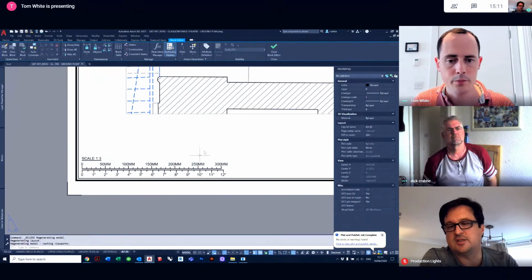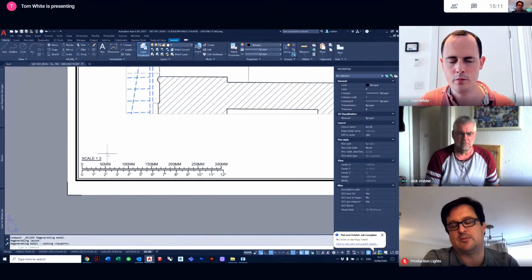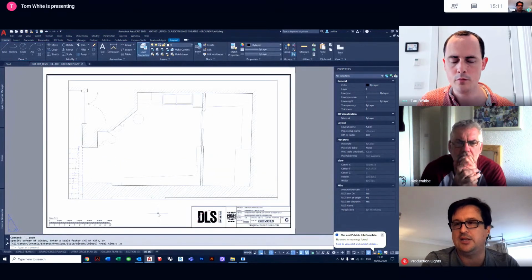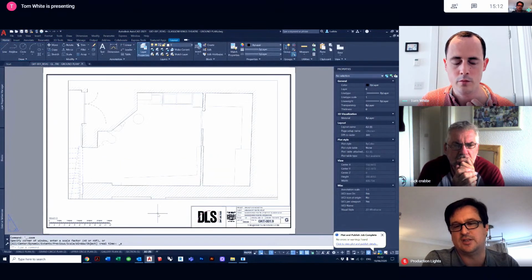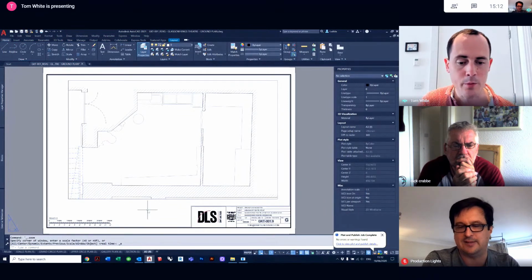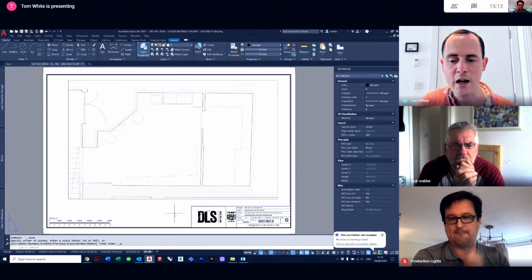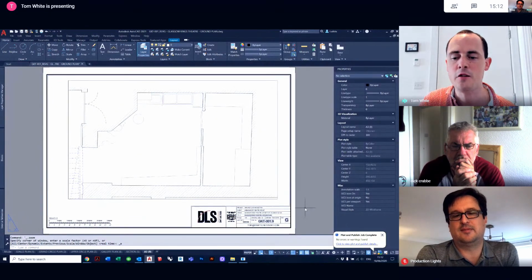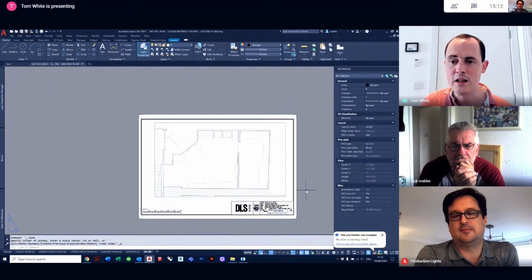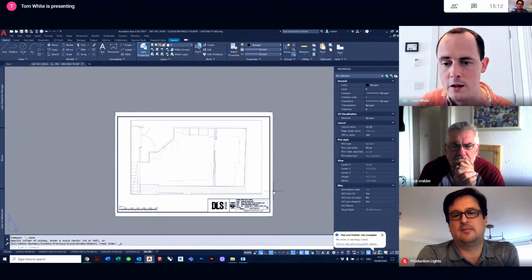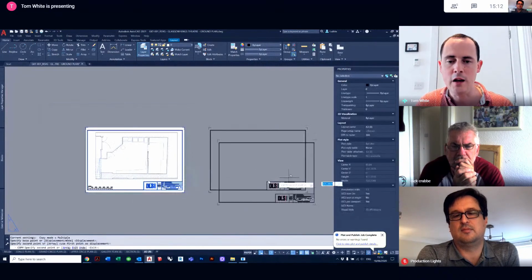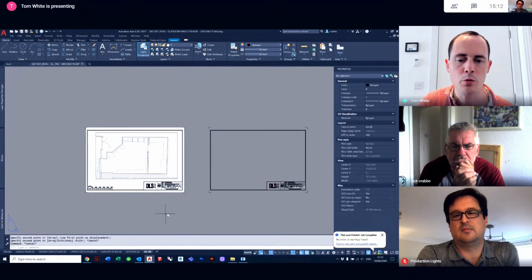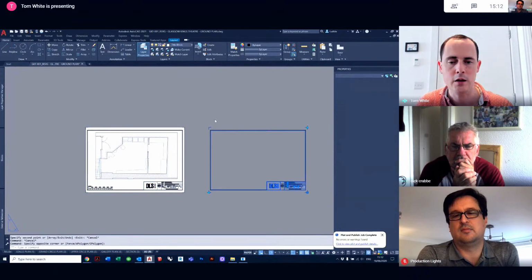Tom, do you think you could also quickly talk about, you've got AutoCAD for Windows open, which I think most people are using, about setting up the page in a layout? So when you went to plot, you had the right paper size and everything. Yeah. So what we have here is, I've cheated. Before the lesson started, I set up an A3 layout. When I say a layout, the A3 piece of paper is the white area. The grey area is a non-area. I could, in theory, if I so desired, copy this over here and print the PDF. It will still only print the white area. It won't print this on the right-hand side.